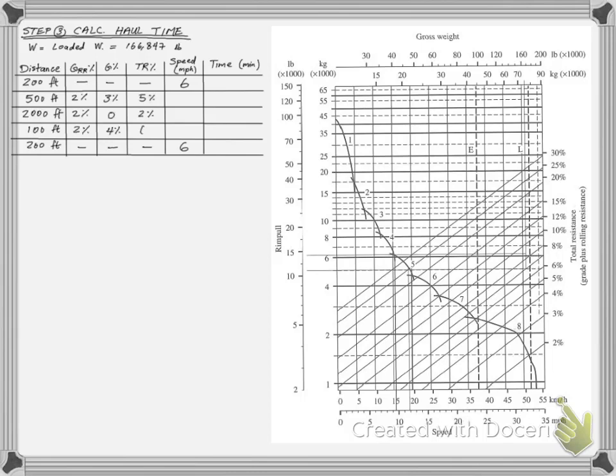The other segments will have the same rolling resistance, but different grade resistances. We add up these values to get the total resistance, which is the greatest for the 4th segment. The time calculation follows the simple distance and speed relation shown, which I'm showing how to apply for the first segment, which is the same for the last segment. Always be careful when dealing with the units.